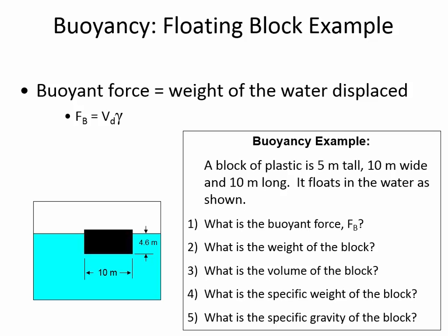So then you've got to be really careful on how the wording goes, because then you need to look to see, are they saying what is the specific weight of the object overall or of the material? So this is plastic, this is air. So did they say what's the specific weight of the cube? And if it's of the cube, then you just do the same thing that we just did. You just only have to look at what's underneath the water line, etc. But then if they said what's the specific weight of the plastic, then you'd need to say, all right, well, I've got a certain mass of plastic here and I've got a certain air volume, and you'd need to subtract the air volume from what's being displaced.